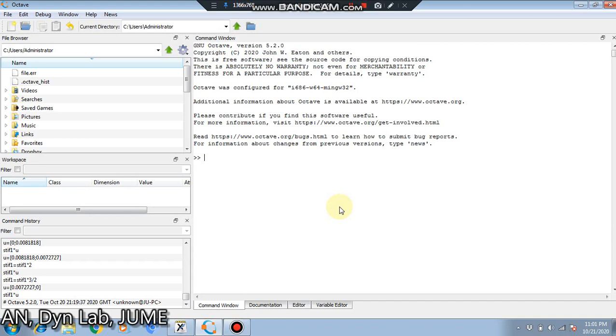I would definitely suggest you all use Octave, and here also we will be using Octave. See how simple it is. Suppose we want to make this k a matrix. So we want to assign a matrix to this variable. Let us call it stiff. So stiff is the stiffness matrix, and say it is 1000, minus 1000, semicolon, minus 1000, and closing the bracket, and you enter.